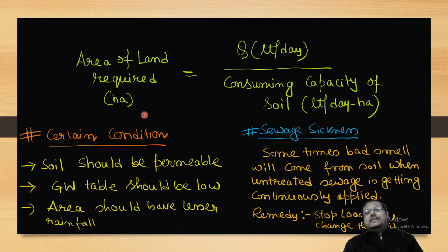There's a thing called as sewage sickness. Sometimes bad smell will come from the soil when untreated sewage is getting continuously applied. Remedy: stop loading, change the soil. That is called as sewage sickness.